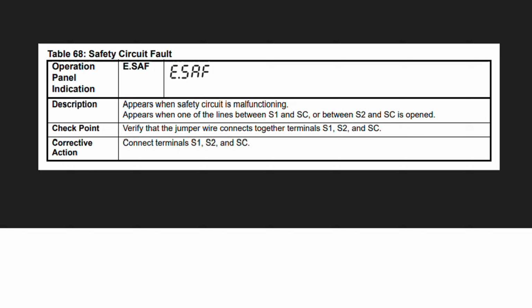Please verify that the jumper wire is connected together at terminals S1, S2 and SC. Please connect a wire between S1, S2 and SC, and it will resolve this alarm. This alarm happens because of this reason.